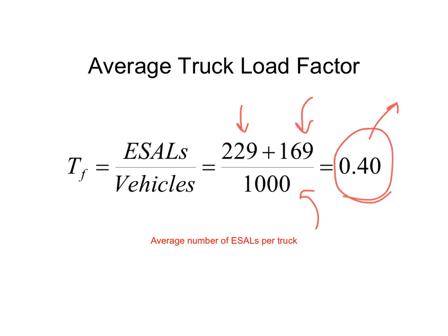This factor means that if you are provided with the number of repetitions, or more simply, if you are provided with the total number of traffic moving on the pavement, that traffic multiplied by this factor will directly give you the traffic in terms of standard axle load. Here you don't require any vehicle configuration or any load configuration data. Just the total traffic moving on the pavement multiplied by this factor will give you the traffic in terms of standard axle load.